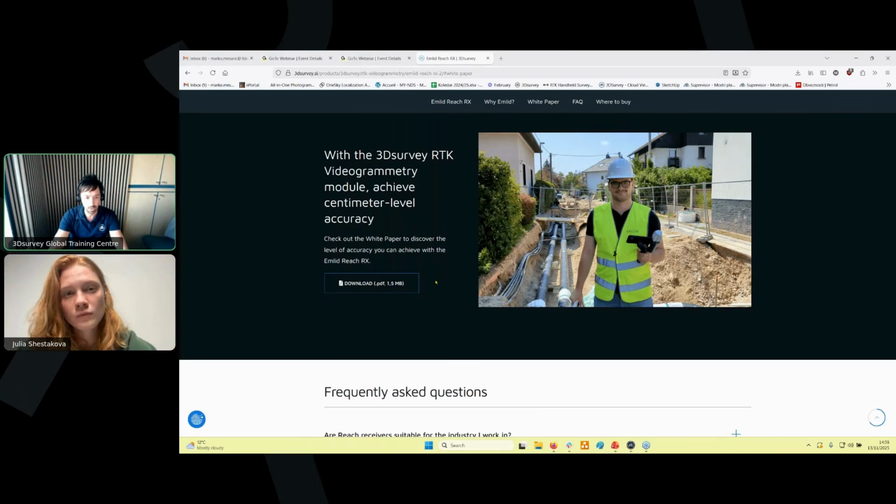Okay, Julia, do you prefer any other apps to run? No, I also like to use the mock location. I was also using this N-Trip app. It's indeed pretty easy. You just pair the devices via Bluetooth, and later on you use exactly the same settings for configuration.